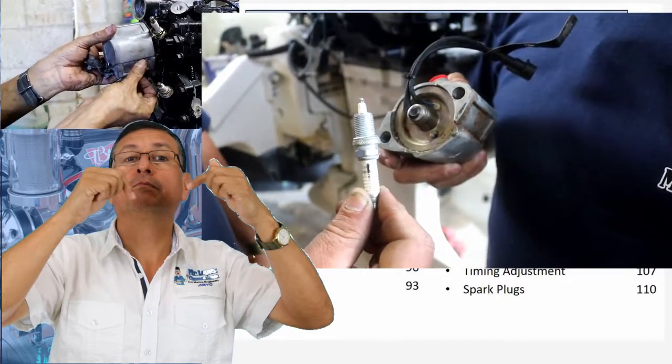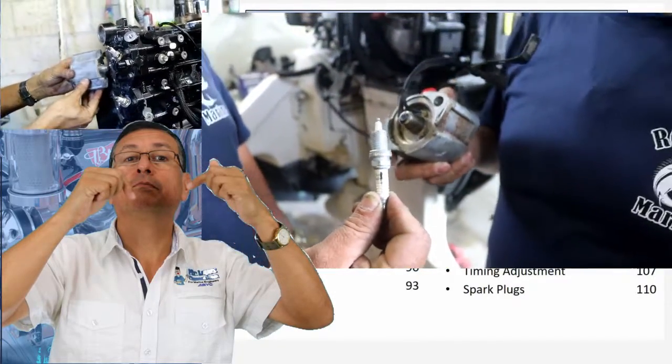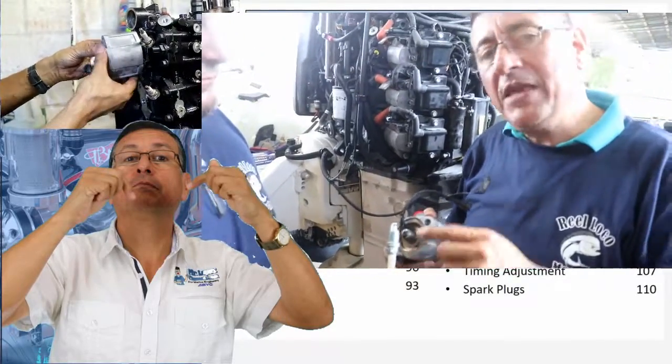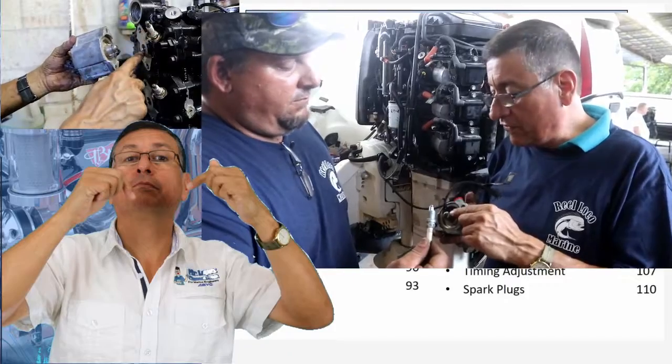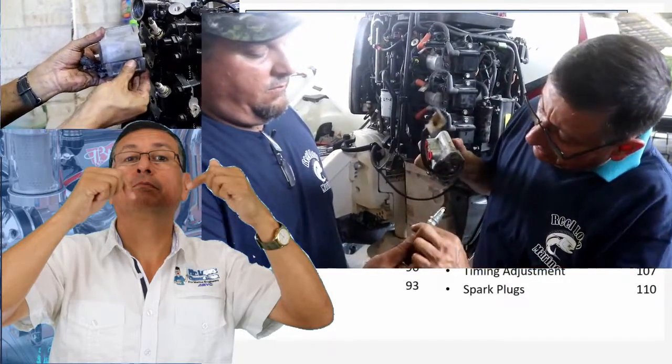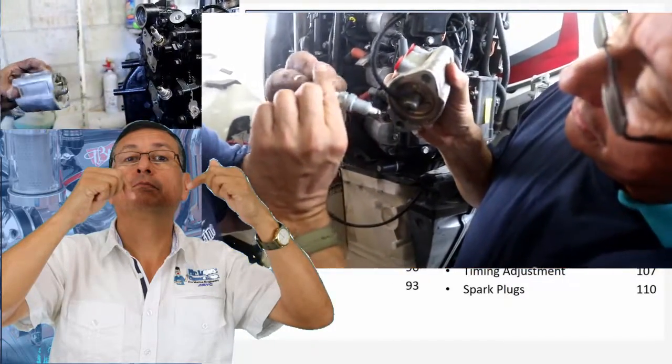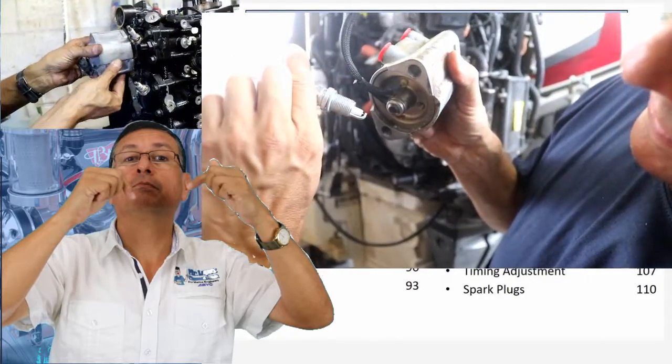Oh, incredible. And what is the symptom? Misfiring. Oh, nice. It's only because the position of the spark plug is not appropriate in front of the injector. Normally, it's like this, no? In the combustion chamber. Correct. Yeah, you want it facing like this. That's perfect, the open electrode.